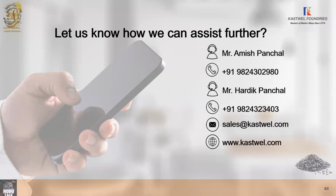Ranjit, I've understood the problem a little bit. First thing is, the temperature is high and the metal weight that is to be poured into the mold is also high. Then maybe you can give 2 layers of coatings on the core. The first layer is a zircon coating, and the second layer is a graphite coating. And when you're using the graphite coating, make sure the graphite coating is made out of high purity graphite and does not contain any subversive elements.